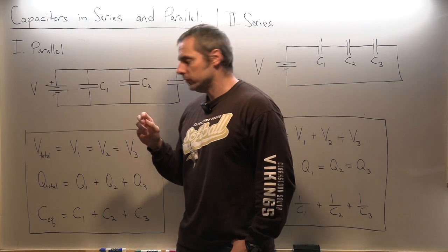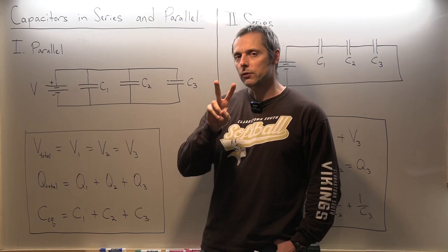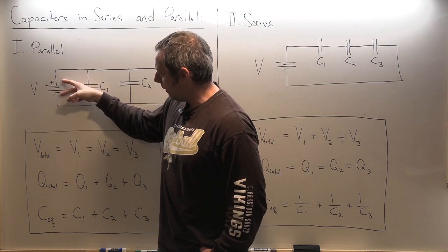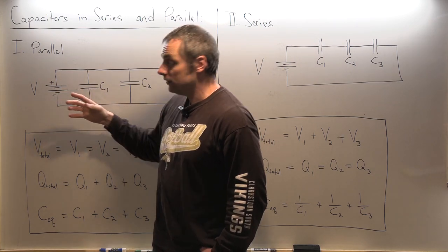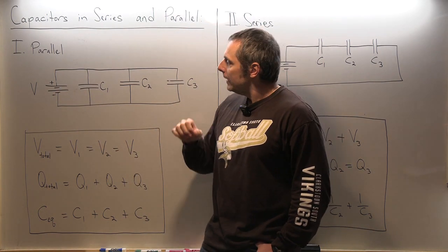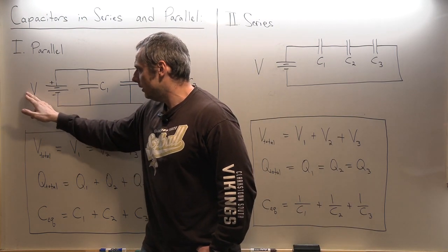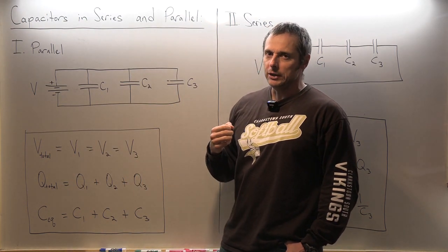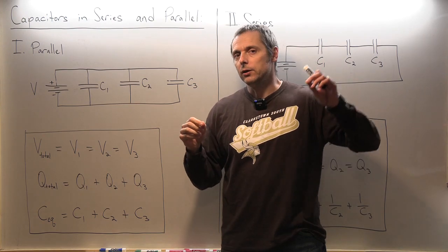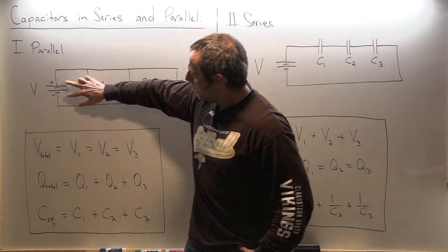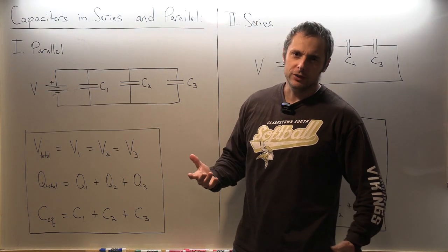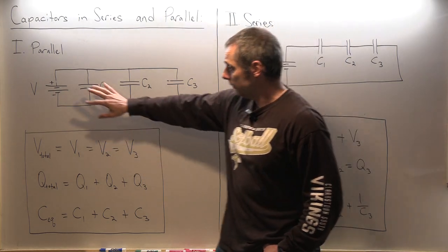The other thing I want to point out, again as a reminder, is that voltage is always from one point to another. A battery has to have one prong and another. So this is the voltage, say it's a 9-volt battery, 9 volts between these 2 terminals. Another minor point: we drop the delta V in circuits. In electrostatics, voltage is considered V when you compare it to infinity. When you compare one point to another, usually there's a delta. But in circuits we just call it V for convenience, though we're really talking about delta V here.